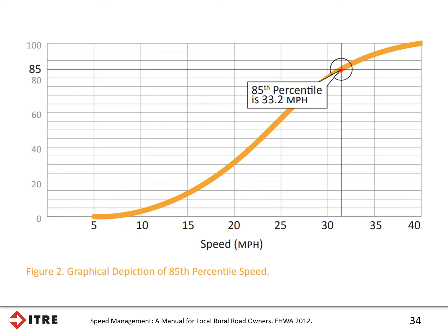The use of the 85th percentile speed is based on the theory that the vast majority of drivers are reasonable and prudent, that they don't want to be involved in a crash, and they desire to reach their destination in the shortest possible time. A speed at or below the 85th percentile under good weather and visibility conditions may be considered the maximum safe speed for that location. That's generally how traffic engineers have approached the 85th percentile speed.